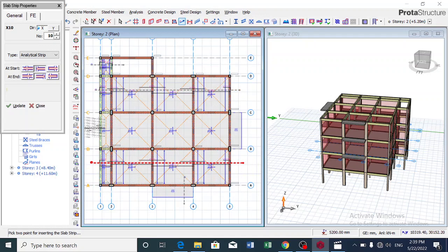Now for this particular line over here, we start with a discontinuous end, which is an outer end, and it ends with a continuous end, which is an inner end. So it's outer end, inner end. So we click, we drag, we hold our control to give us a straight line, we click and stop here.